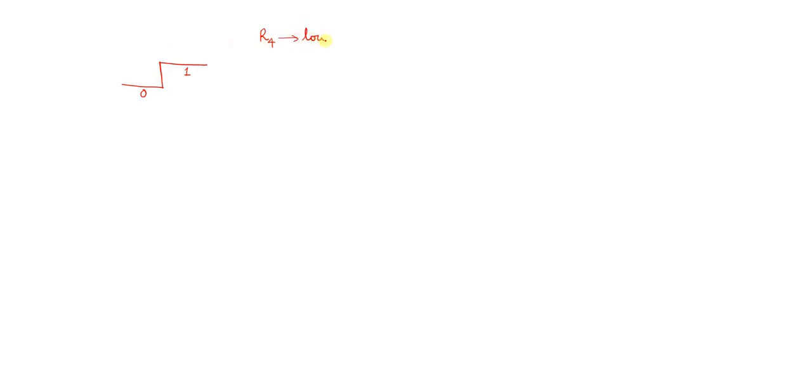So initially if it is logic low, then we will store the value of register R4 with 0x00, and if it is logic high, then register R4 will be having a value 0xFFFFFFFF. We know that these registers are 32-bit registers, so we will store the value 0xFFFFFFFF.